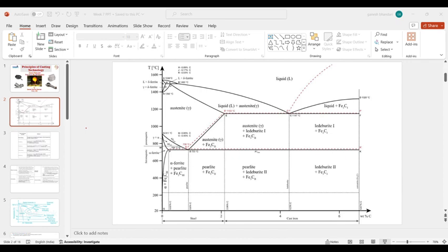So in homogenizing treatment, in the homogenization heat treatment of non-ferrous alloy, generally we carry out homogenization treatment on aluminium alloys. When we go with age hardening of aluminium or heat treatment of aluminium alloys, first we go with the homogenization process. In homogenization process, homogenization of the composition occurs spontaneously through diffusion. Yes, this is correct, because we are trying to homogenize our system.